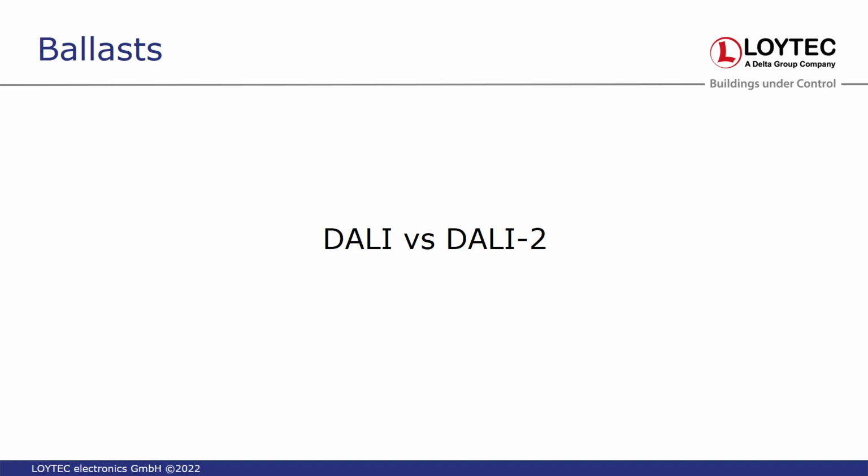And also, what Hans showed, there are these 8-bit and 16-bit commands. In DALI 2, you can also have 24-bit commands, so longer commands. When you do these DALI 2 tests, the test makes sure that your device is able to handle all of that, and is able to cope with these long frame commands.